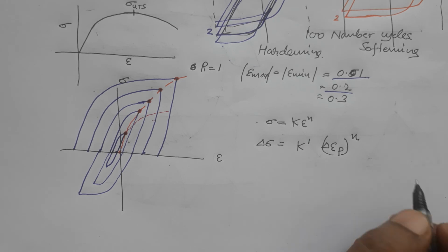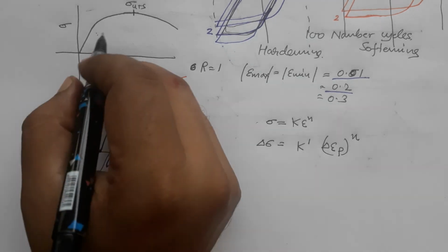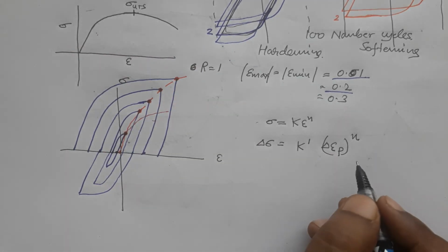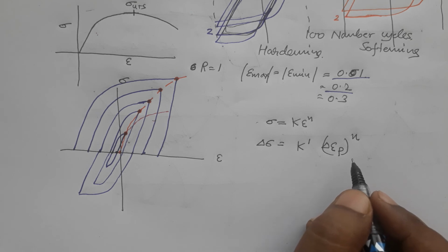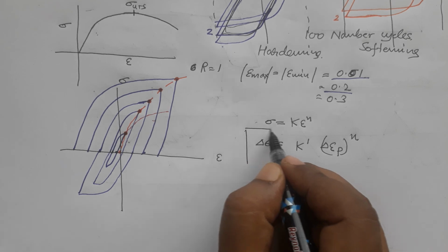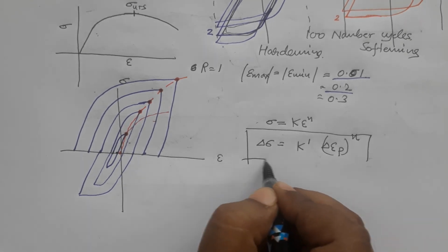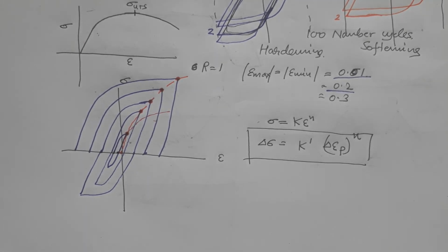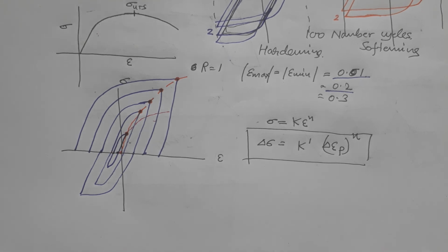Okay, because of course we are talking about the non-linear part, which is only plastic strain, we are not talking about elastic strain. So we can have a similar equation in cyclic loading also. So we can have a power law relationship.